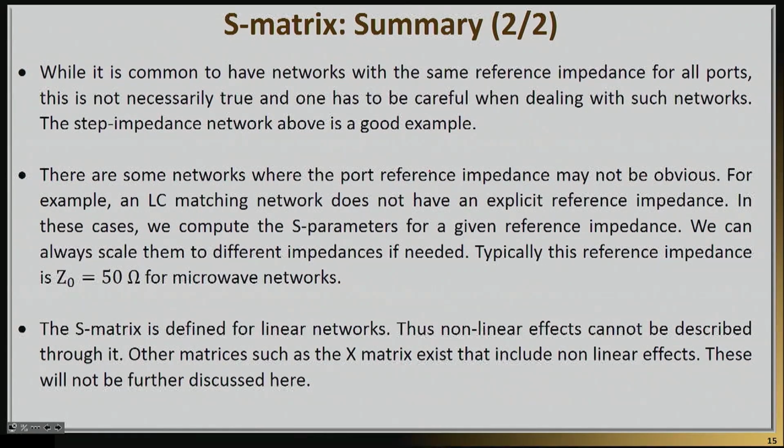Lastly, something that gives trouble to a lot of us is that the S matrix is by definition linear. However, a lot of the networks that we see are nonlinear. So what you do, if you need to characterize nonlinearities, is either make assumptions about weak nonlinearities and then use the S matrix, or use other matrices that are made specifically for nonlinear networks, which we're not covering in this class.